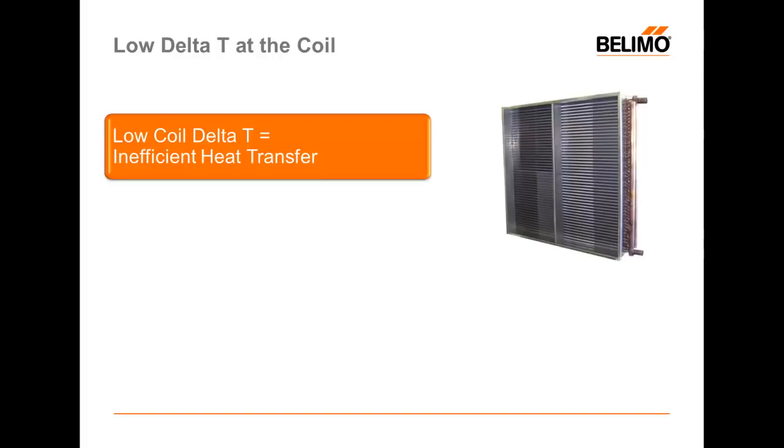When you send very cold water down to your chilled water coil, if you do not transfer enough heat, that water will remain cold and get sent back to your chiller at a colder temperature than is designed. This is what's known as a low delta T. It's inefficient for several reasons.